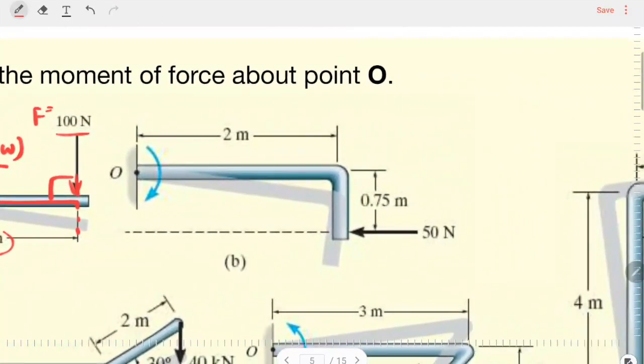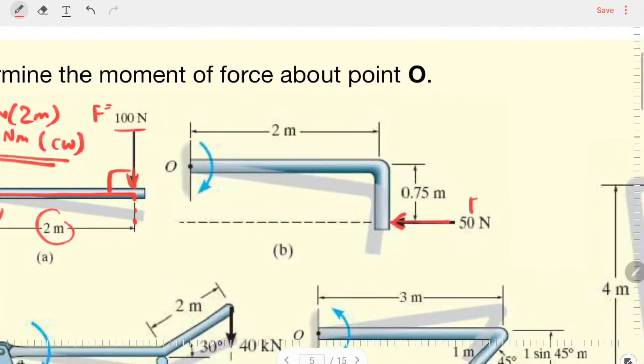Okay, let's look at the second picture. This is the direction of the force. So if you want to know what is the distance of the line of force to the rotational axis, you just elongate the force line until it reaches the rotation axis, at a point where the line is perpendicular or 90 degree with our line of force, so that would be our D or distance.